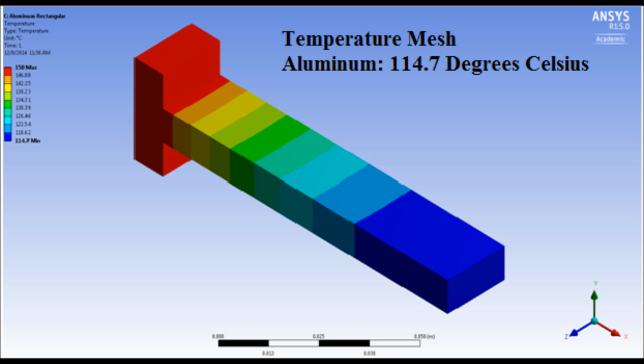Using NX, we modeled our fins with a length of 10 centimeters so that it was long enough to be considered infinite, then imported them into ANSYS Workbench. We then computed a temperature mesh and a heat flux mesh for each fin and material.